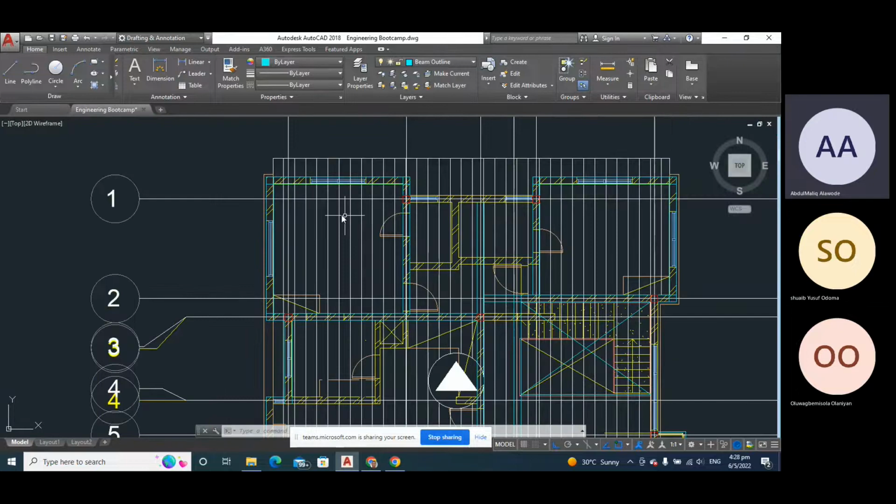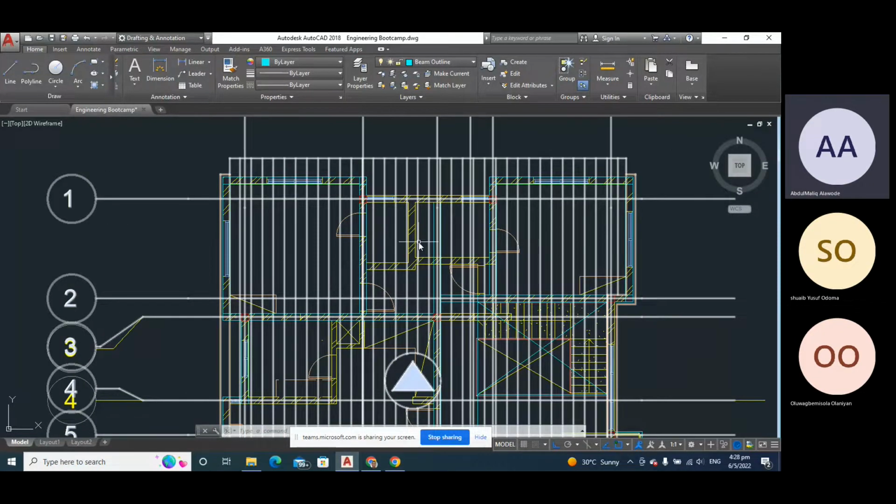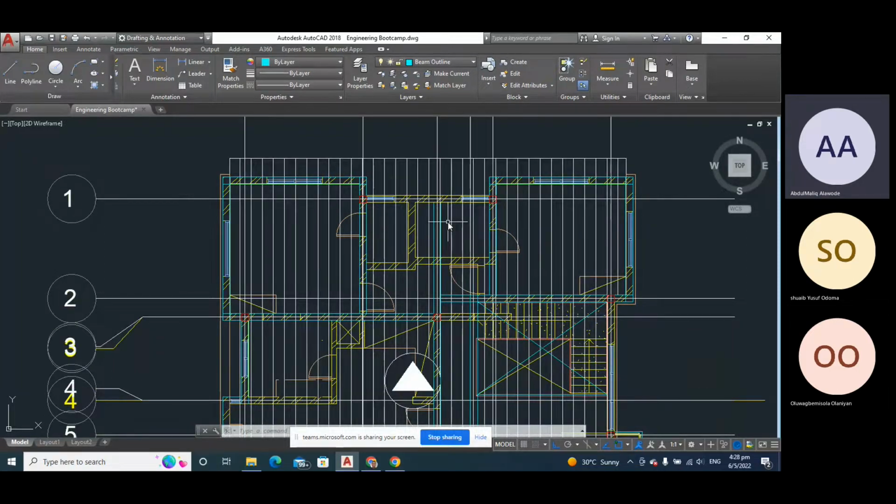So that's the mentality we are going to use while drawing our roof layout. We'll not forget to keep our beams as hidden as possible. You still have your ceiling that is going to cover it, but anything might happen, they might want to change something in the future.